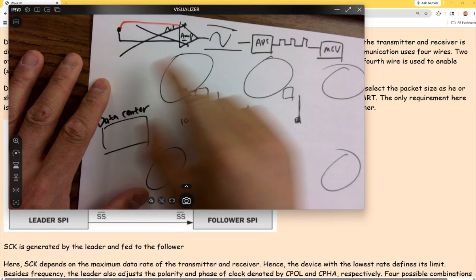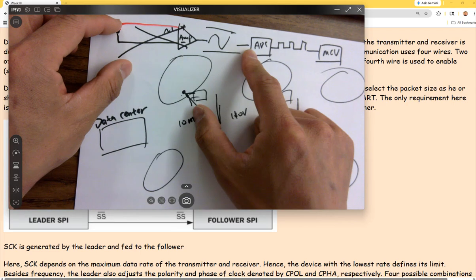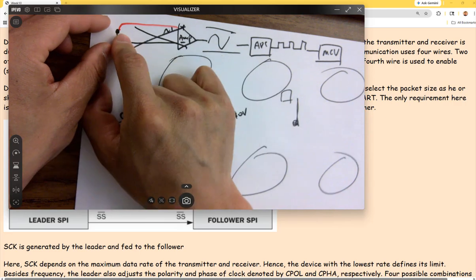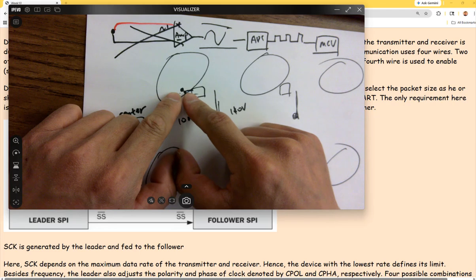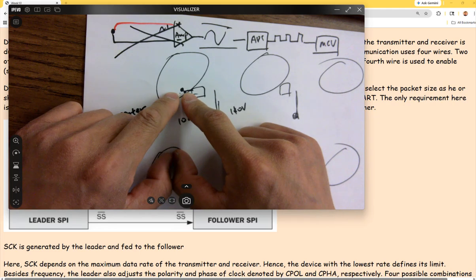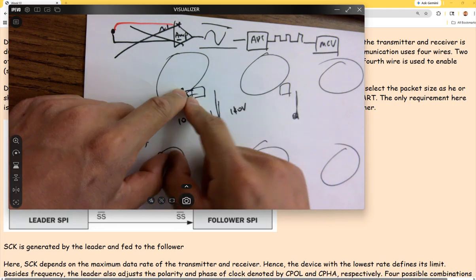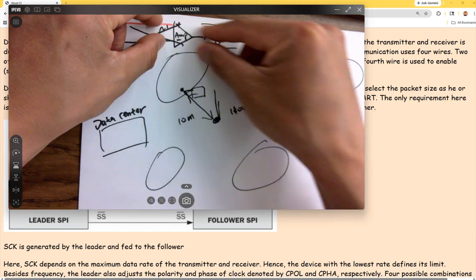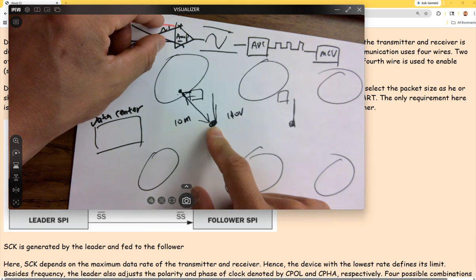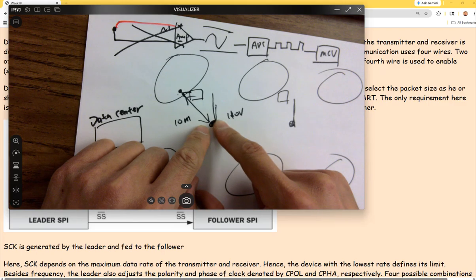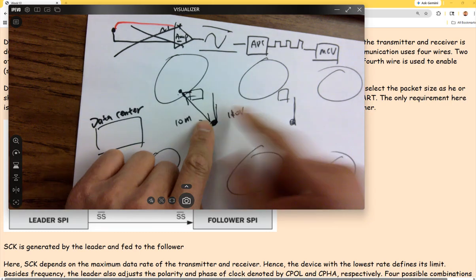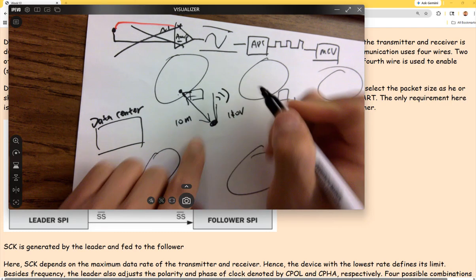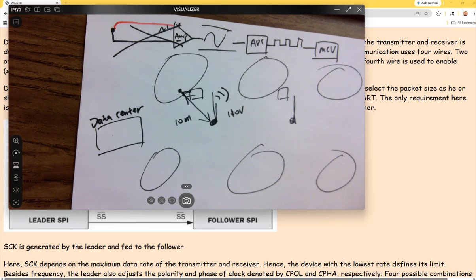So what about, hey, I don't just put the amplifier and ADC close to it. I just have a little thermocouple sensor. It's a little tiny piece, and I drill a hole and place the sensor into that hole, and it's just able to have contact with the water. And then I just use a wire, 10 meters of wire to the light pole, and then I have a little box attached to the light pole, do all the amplification and digitization, and then the MCU, so I can send it to the wireless center somewhere else over here. What about that option?